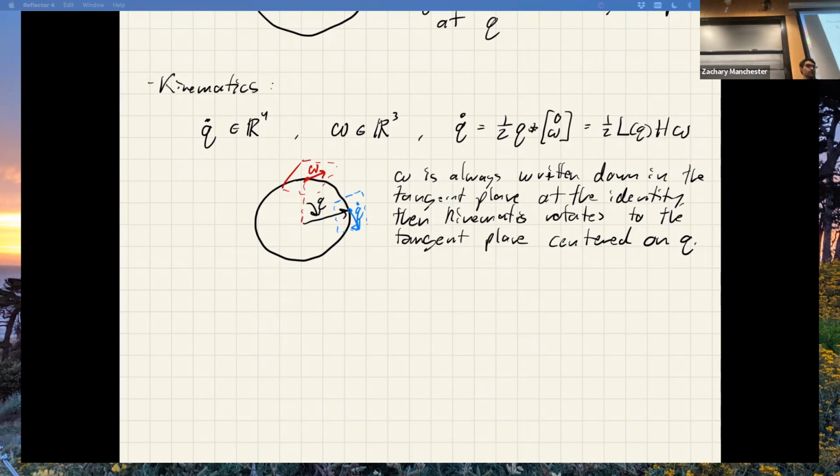The way you know they're not a vector is if I say I have a vector of Euler angles, like roll 90 degrees, pitch 90 degrees. If I try to add two of those together and switch the order, roll 90, pitch 90, I'm here. If I flip the order and try to add those vectors, I'd get pitch 90, roll 90. It's a completely different answer, right? They do not add like that. They don't commute, right? I can't add them together so they're not vectors.